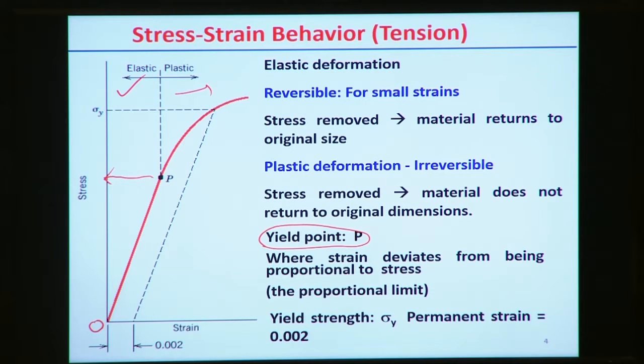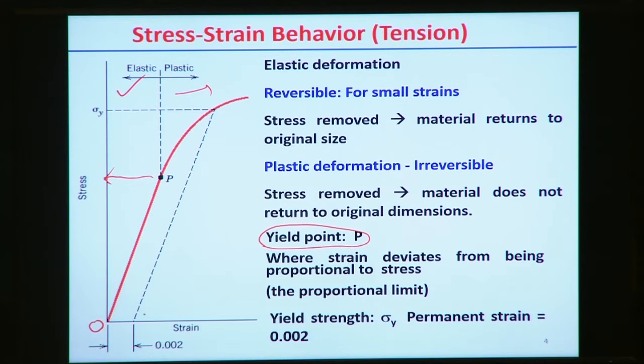But in certain cases, for some other material, or maybe a very large group of materials, there may not be a very clear transition zone from elastic to plastic deformation. So that transition zone is very difficult to identify when you simply look into the stress strain diagram of that specific material. So in this case, we generally consider the offset yield point. That offset yield point is defined on a permanent amount of strain, that is 0.002.